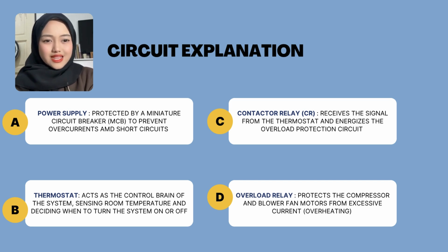Third, we have the contactor relay, CR. CR receives the signal from the thermostat and energizes the overload protection circuit. Last but not least is the overload relay. The overload relay itself protects the compressor and blower fan motor from excessive current.